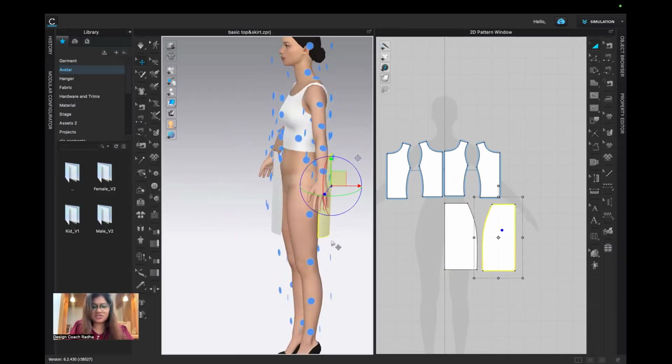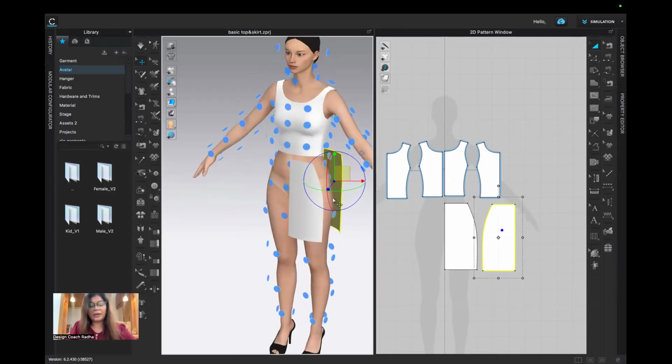I want to do the stitching only on the right side. So which tool? N, that is sewing, segment sewing. Just click on this and scroll, scroll, scroll till you find the parallel lines and click. So this is done. The stitching is done. We do not need to do the top side, we just want the right side part.